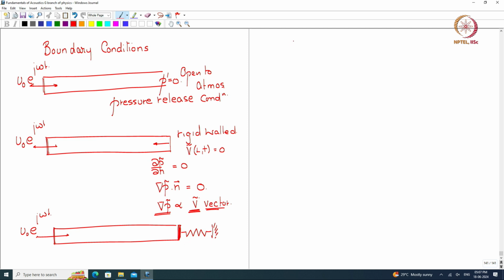So here this is like saying the pressure divided by the velocity, okay, into let us say the cross section area to make it a force, that is the end impedance Z tilde ML, which in this case would be j times m omega minus the spring constant by omega. Okay.